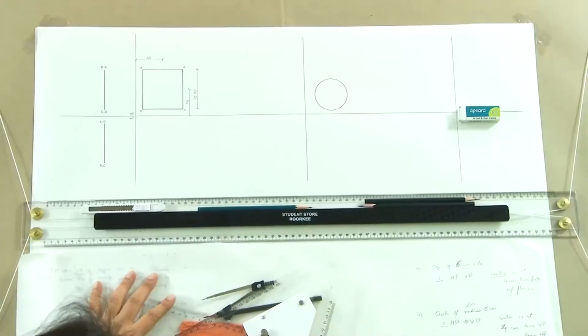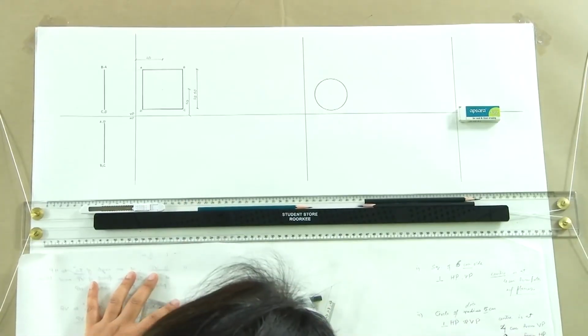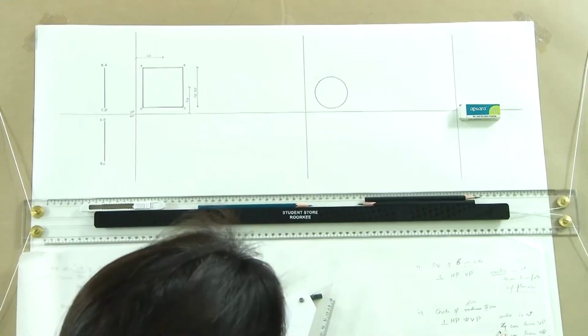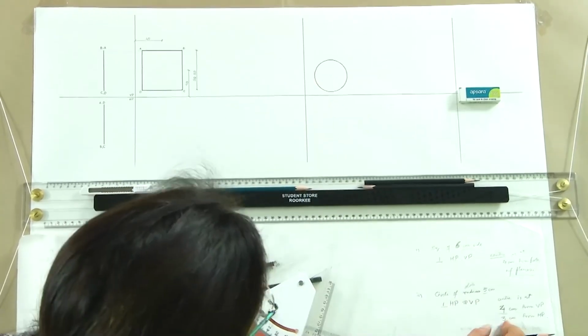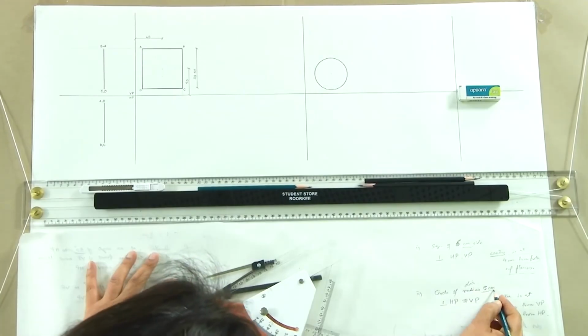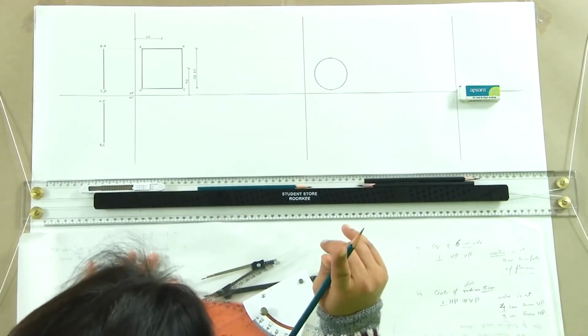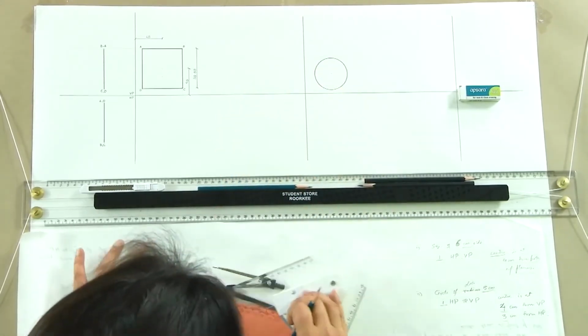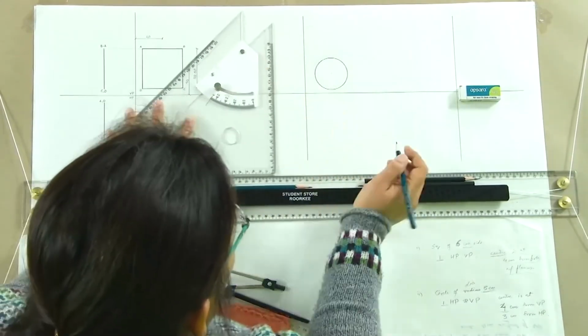If you follow the process that I am taking for drawing this, you will see that any dimension which is given here, I will be measuring only once on the sheet. So, I measured this 4 centimeter only once, I measured this 3 centimeter only once, and I have measured this diameter of 5 centimeter, which is radius of 2.5 centimeter only once. Once I have this dimension here, all other dimensions will be referred or derived from the same drawing, which is how geometric construction should always work, right.